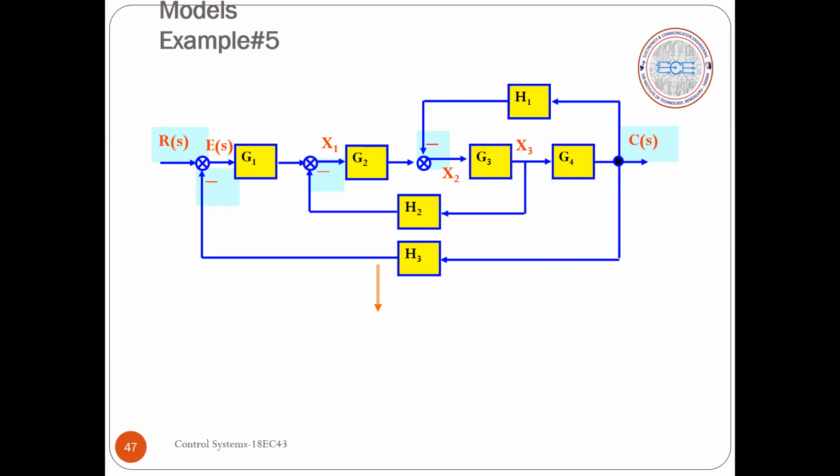So here, if the block diagram is given, we have to convert that to a signal flow graph. For that, we have to identify how many nodes we require and how many connecting branches. So how many nodes, that's a very important parameter. Here, the number of nodes is equal to the number of inputs, number of outputs, number of summers used, and number of takeoff points.